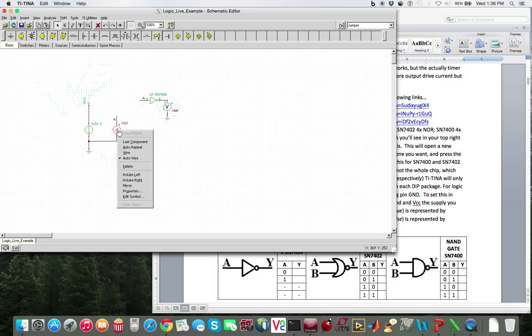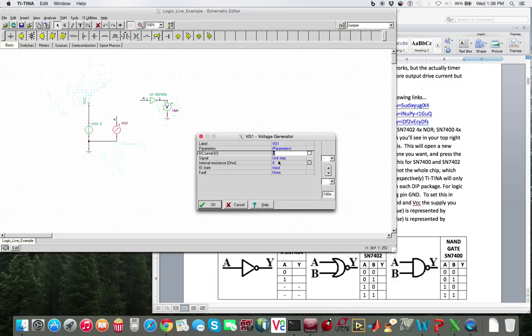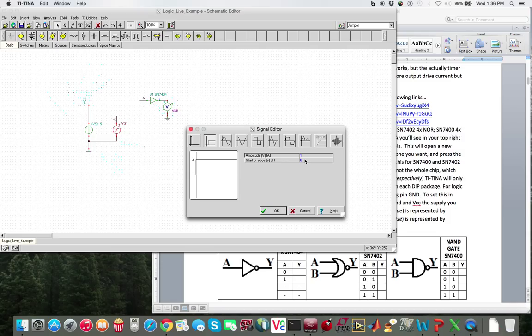So if I right click on the voltage, the waveform generator, what we need to do is go and click on the signal, and you'll see little 3 dots that generate. Go ahead and click on that. What we want is a square wave, and I forget what frequency I asked for, but let's go ahead and do 50 Hertz, and you can leave the rise and fall time, but let's create the amplitude at 2.5 volts.